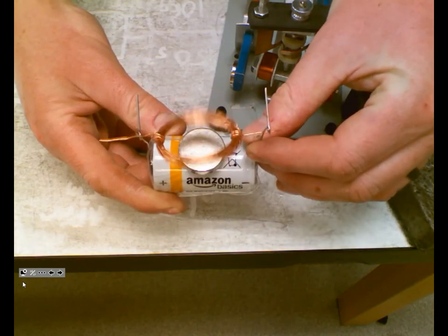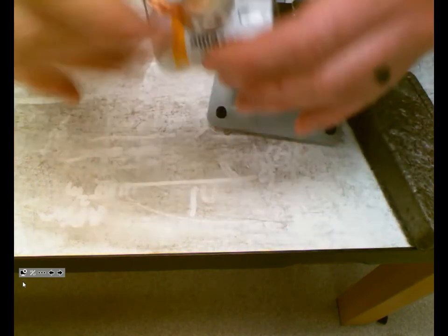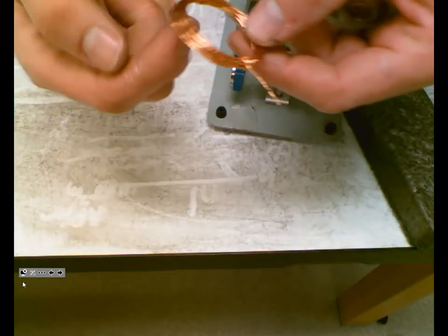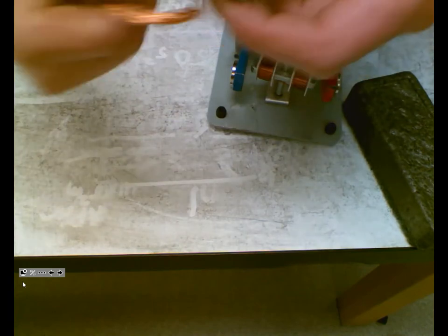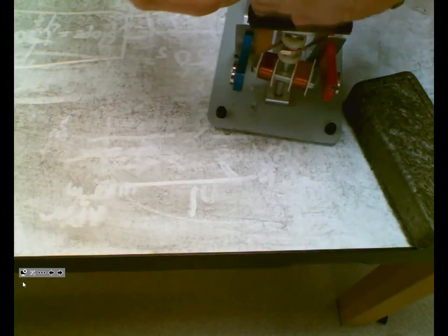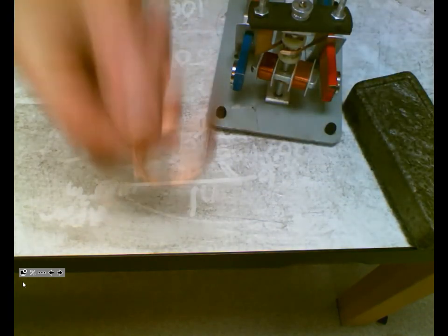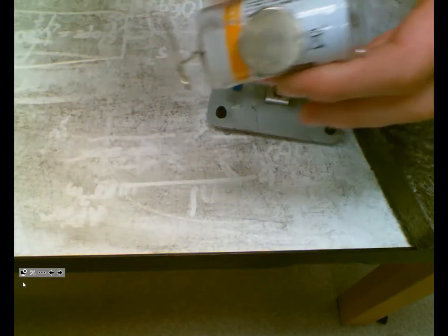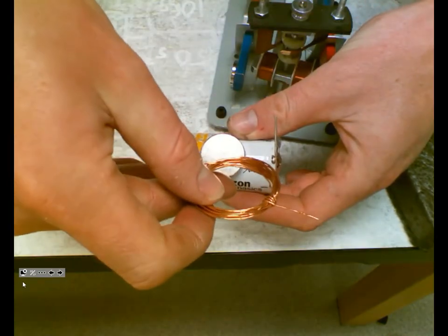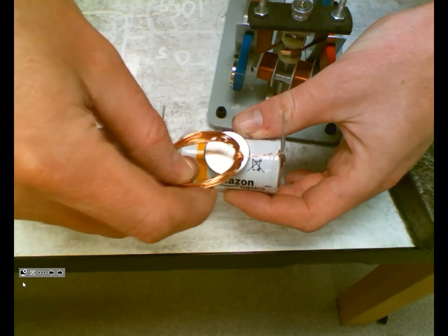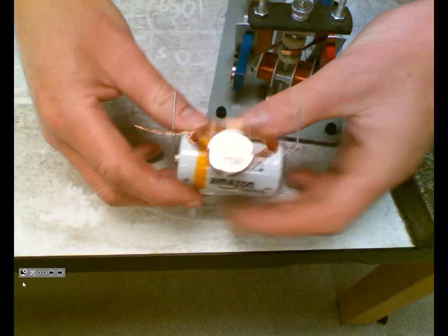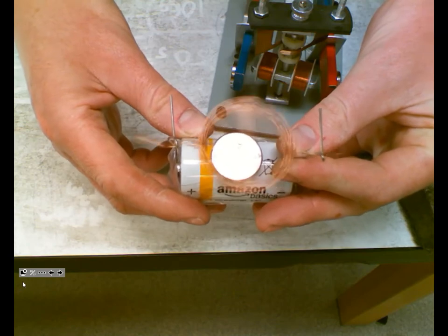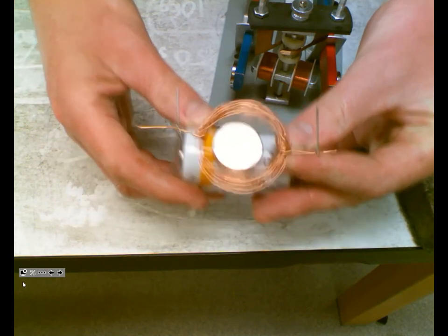So what's happening in this situation is inside of this coil, we get a magnetic field. When it's attached to the battery, we get a magnetic field. And we have a north side and a south side. And this magnet has a north side and a south side. So the induced current in this coil of wire interacts with the magnetic field from this permanent magnet, and you get motion. And this is how a motor works. Here it goes. Okay, that's how a motor works.